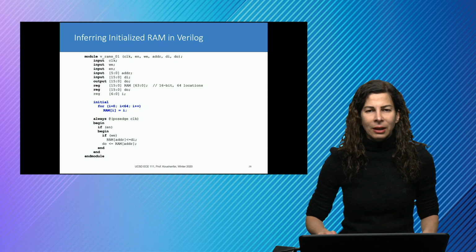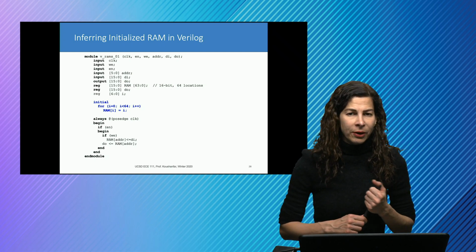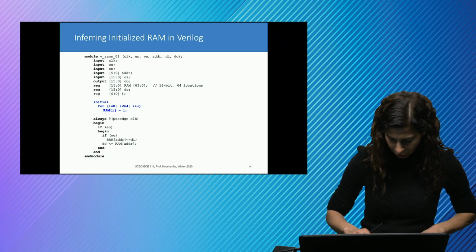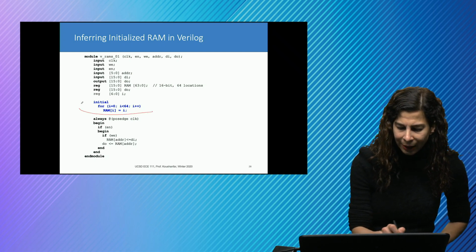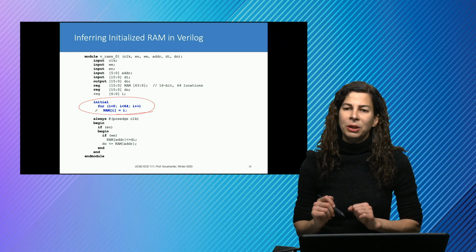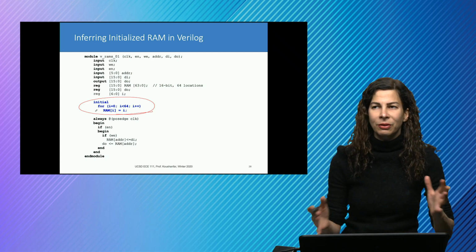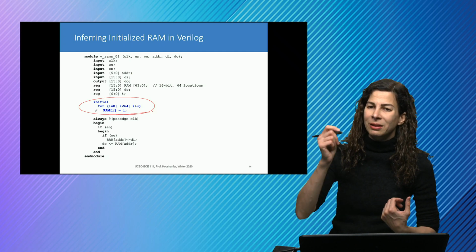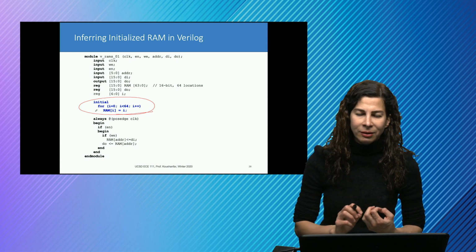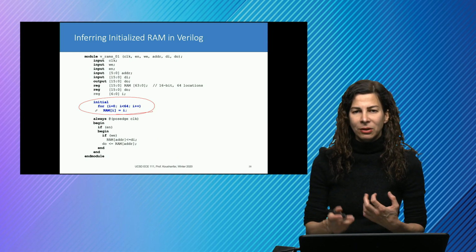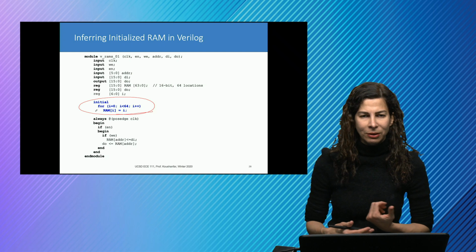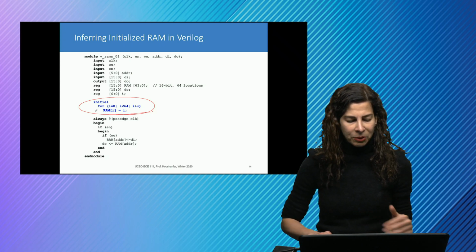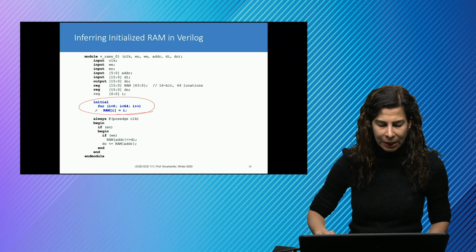So this is another RAM in Verilog, which is inferred, and this is initialized. The way this is initialized is using the initial command, and as you see here, the initial command is pretty portable, so you could use it on any different board. We are not using any library, but every time you have an initial statement, it only runs in the beginning of the code, and it's a clocked statement. It's a synchronous statement. It's going to initialize the values of this RAM. In this particular example, it's just going to initialize this to numbers 0 to 63 for the 64 addresses that we have.